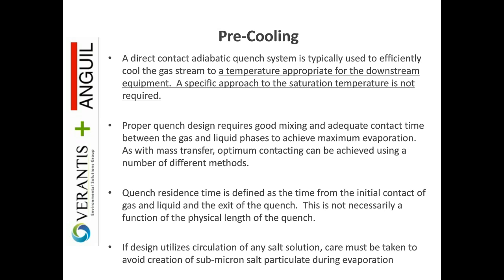It's an important note that sometimes we might think that we have to try to drive the gas all the way to its saturation temperature, but that's not really the case. You just need to drop it to what's safe for the downstream equipment, which would normally be somewhere in the 180 to 220 degrees F range.